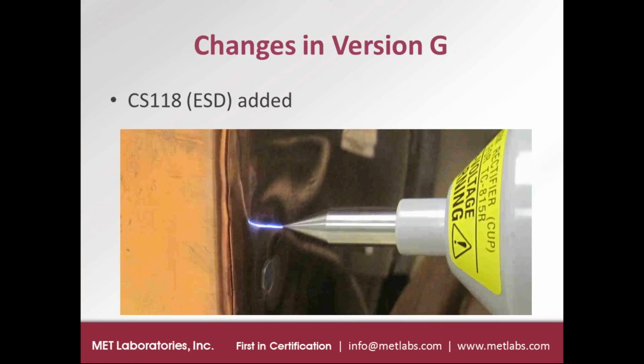And so the next significant change to 461G is the addition of CS118. And again, the CS118 method number didn't exist before version G, so they created the new number and added ESD, electrostatic discharge testing, to 461.